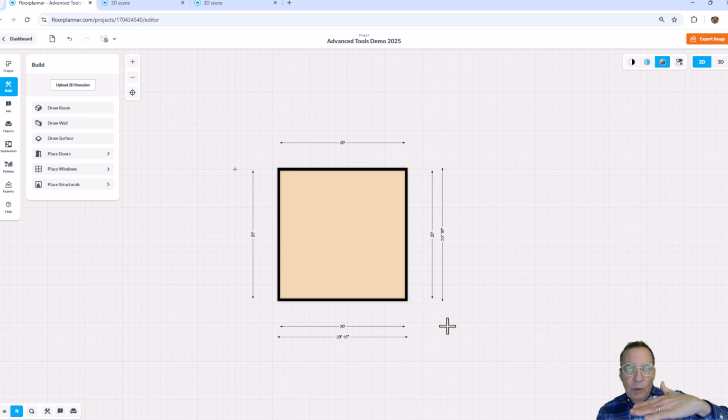The order of that X and Y direction, 20 feet, comma, space, 20 feet, is pretty typical architectural language. So when you see it in a plan, for the most part, it should be the horizontal distance first and then your vertical distance second in a plan view. Well, we just did so and created a specific room if you're comfortable doing so.